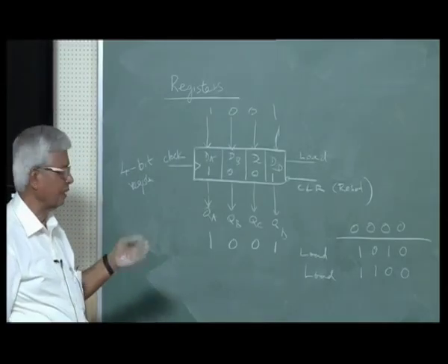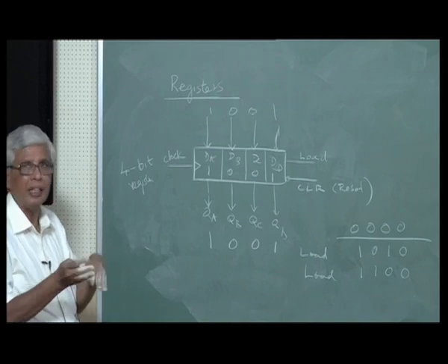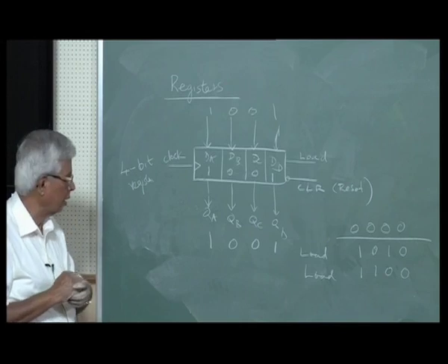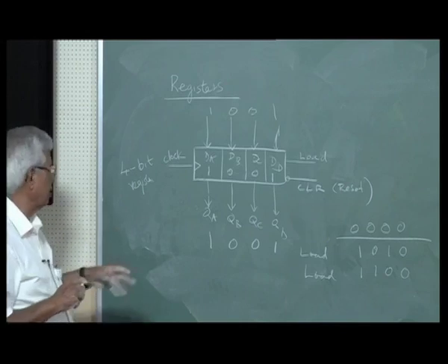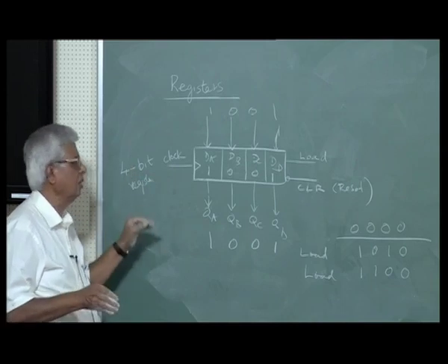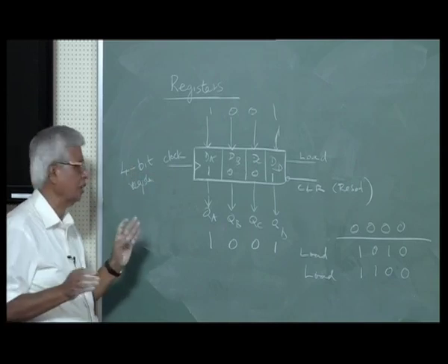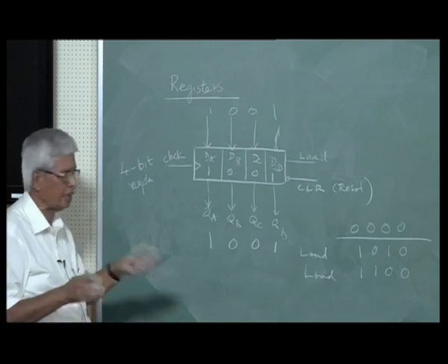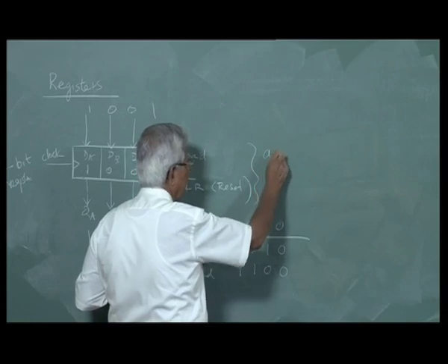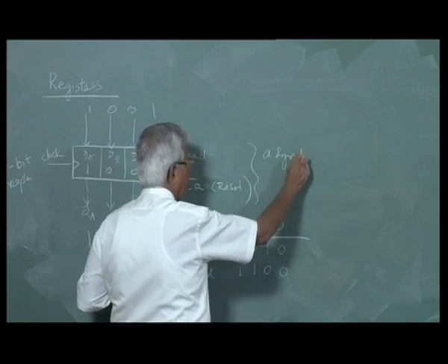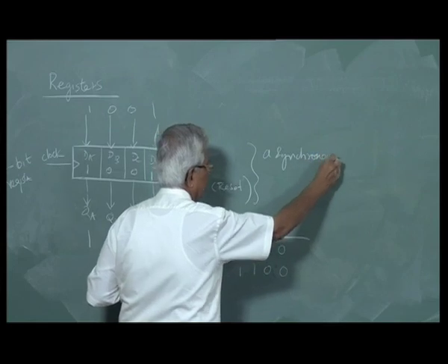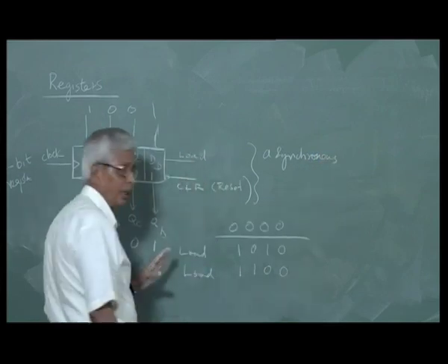Load and reset are generally non-synchronous. They can be given any time, not necessarily with the clock. It depends. Certain registers will have load and clear that have to be given along with the clock. But most registers have load and clear signals which are asynchronous. What do you mean by asynchronous? They can be given any time, irrespective of when the clock comes, usually.